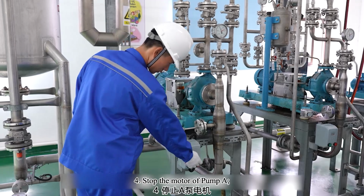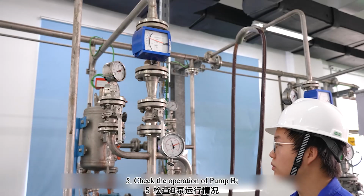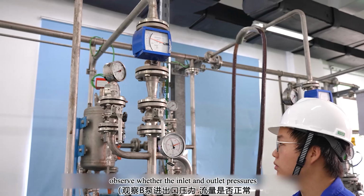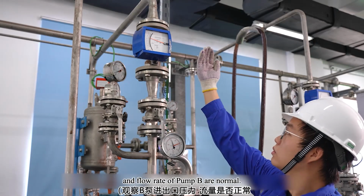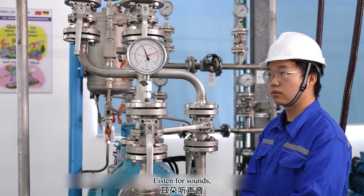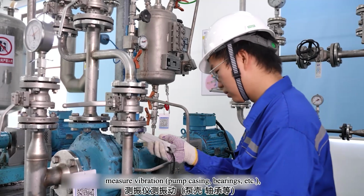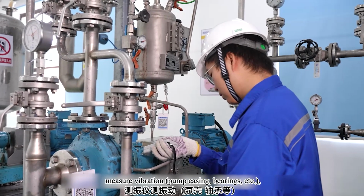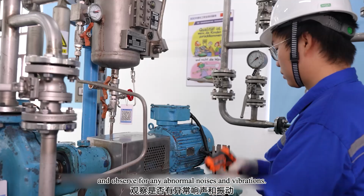Fourth, stop the motor of pump A. Fifth, check the operation of pump B. Observe whether the inlet and outlet pressures and flow rate of pump B are normal. Listen for sounds. Use a vibration meter to measure vibration, pump casing, bearings, etc., and observe for any abnormal noises